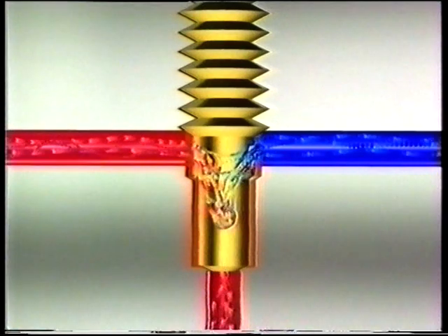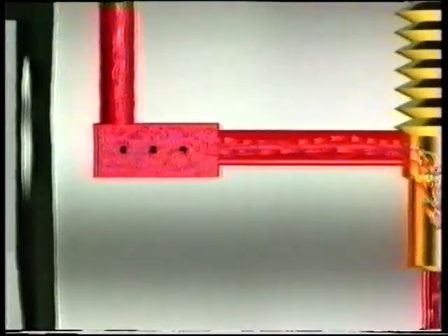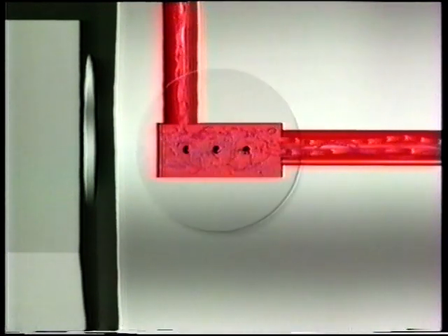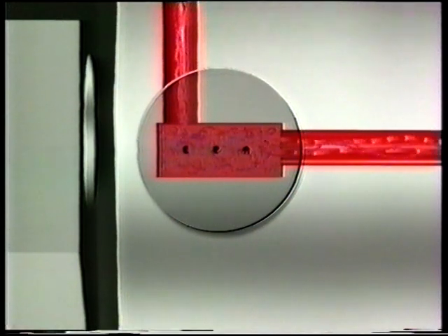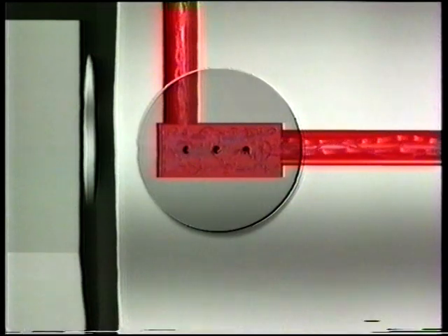As the fuel and air begin to mix in the pilot jet, the mixture may move into a cavity where transitional holes are drilled. This cavity or reservoir will be covered by a Welch plug. The holes shown here deliver the fuel when the engine is idling or under light load. Some carburetors provide a mixing area within the pilot jet itself. Different pilot jets are used in various carburetors, depending on the application.